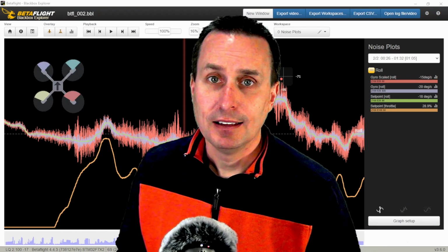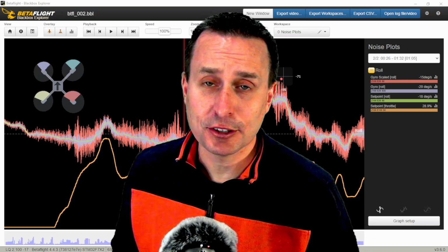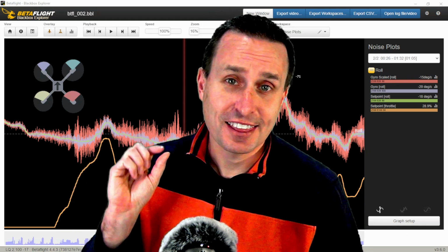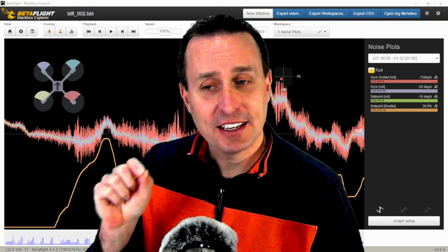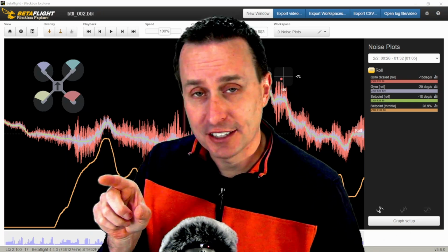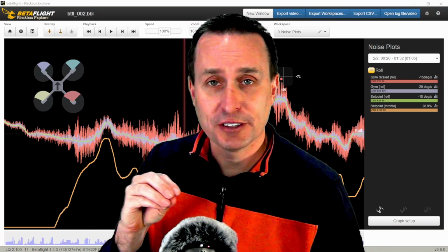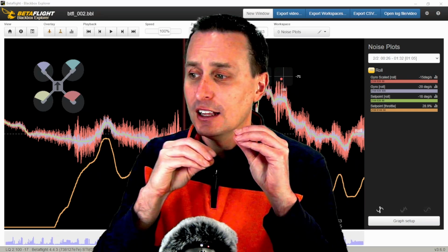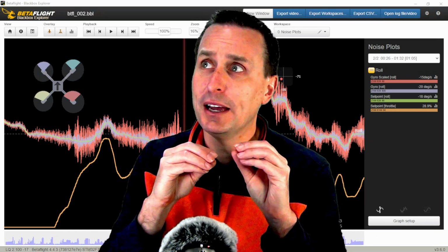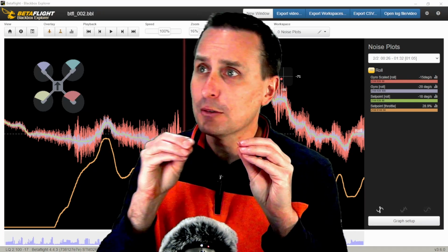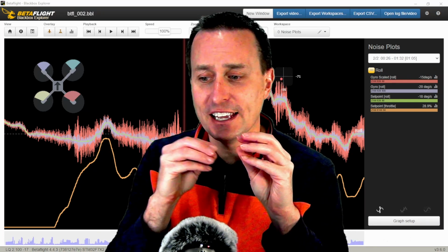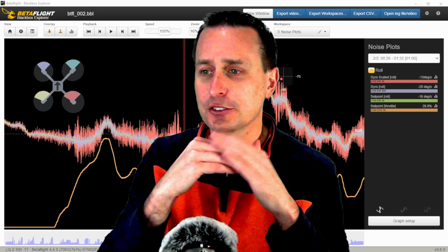Outside of that, it's got to be something shaking around in your quad, so make sure everything is stable. That's my advice. Lower the gains. That should fix it, is my guess. And if it doesn't, if you're down at D gains of a low 25 or whatnot and it's still there, I would just double check your quad. I had somebody the other day where the capacitor wire was yanking, or the way they had the capacitor mounted was kind of yanking on the flight controller or hitting the flight controller.